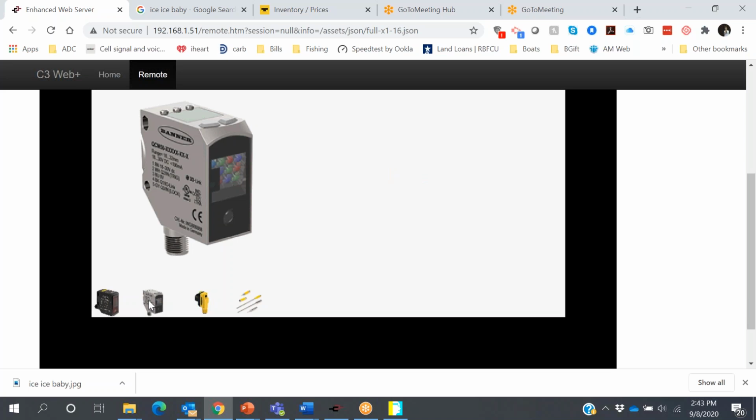So we're getting which color I taught is coming through the IO-Link message. If you want to do more of a preventive maintenance thing and kind of see if your color starts to deteriorate or change over time, you can also get the actual RGB values over the IO-Link message. So as your product is running, you can see if those values start to deteriorate where you need to change out, print, ink, or something like that.